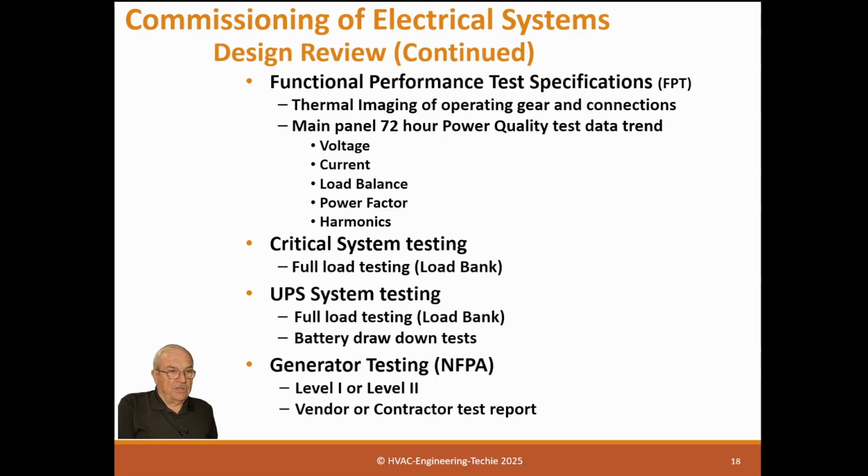Now, NETA is more than an association. It basically certifies technicians to a level of testing, and it's really good. If you get a level 4 NETA test technician, you've got a really good guy. Well, at least he should be, because he's got the knowledge. So that needs to be in there, and these critical system tests are normally done by a third party. There's no reason a contractor can't do it if he has the people.